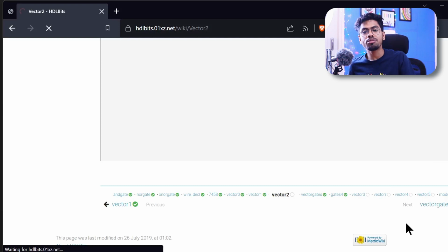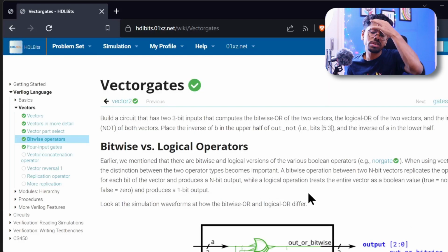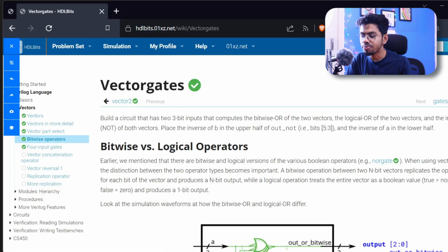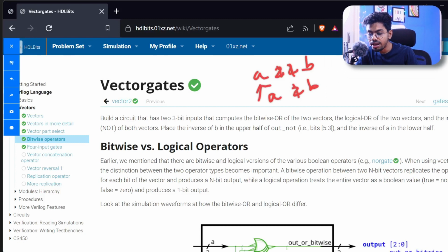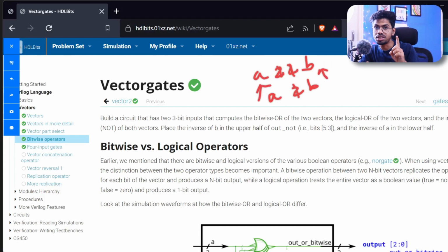It's very important. Actually, one of you asked me a question. Sometimes, in one of my videos, in the second episode I think, I was using double & with a and b to make an AND gate, and in my third episode probably I was using only one & and saying it's the AND gate. Both are different, but in our second and third episodes we haven't seen any difference, because at that time our a and b consisted of only 1 bit, right?